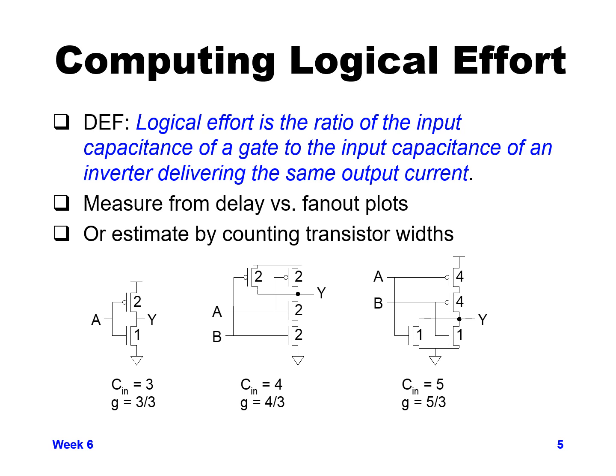Now when we look at a NOR gate, on the other hand, your NMOS are in parallel with each other, so there's a single NMOS between your output and ground, so they stay the same size as a basic inverter, size 1. Your PMOS devices are now in series with each other, which means they need to double in size so that the equivalent resistance between VDD and your output stays the same as a single PMOS would have been. So you need twice as wide of a PMOS because there's two in series with each other in order to keep the output current drive the same. So our PMOS is now size 4, NMOS size 1.